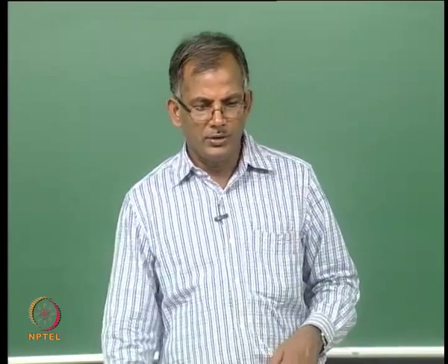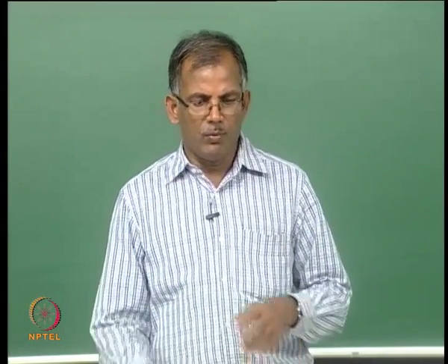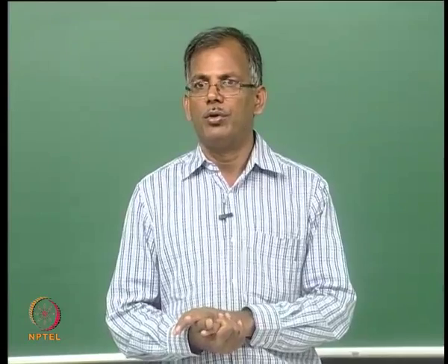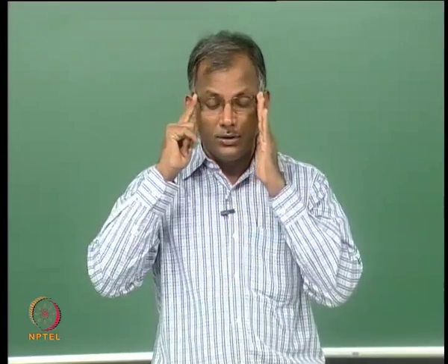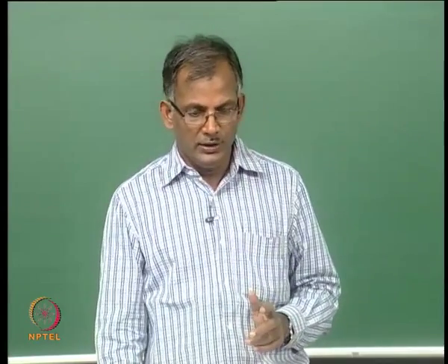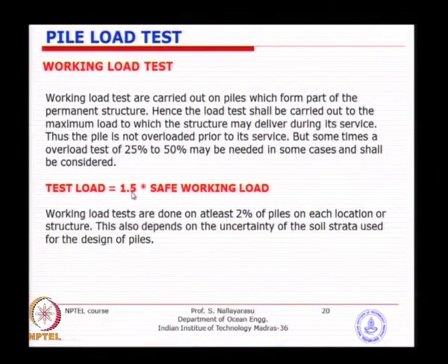Working load test is typically 1.5 times the safe working load. So, we want to go for a slight overloading, but not to the ultimate stage, as long as you want to see the passing of the working load and also have a little bit of margin.